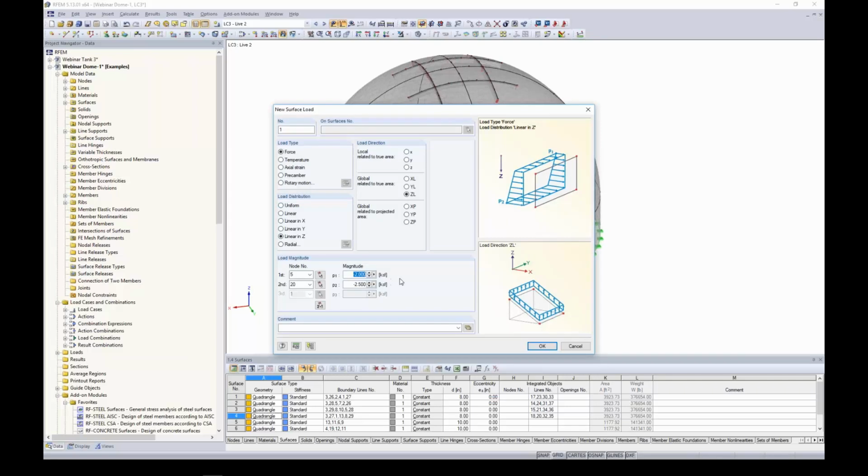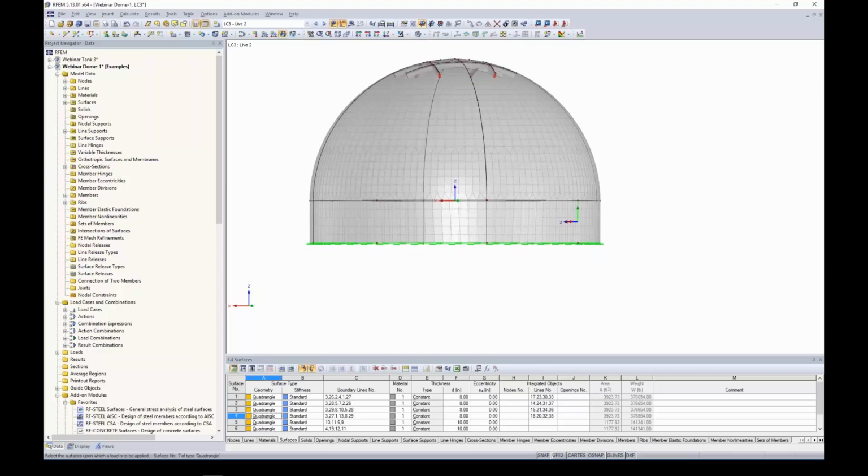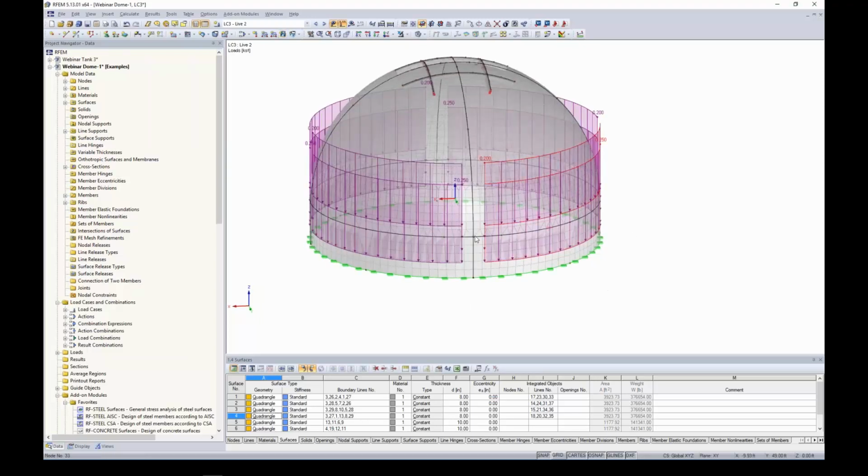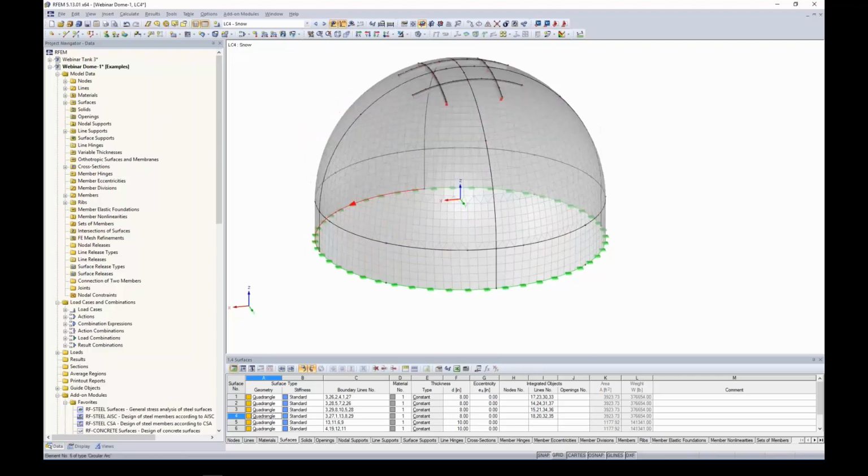The magnitude though will be negative 0.2 to negative 0.25, so much less. The settings are remembered from last time for what's the top of the wall versus what's the bottom. I click OK, and now you'll notice I just select my walls here, and here is my friction load applied to them.